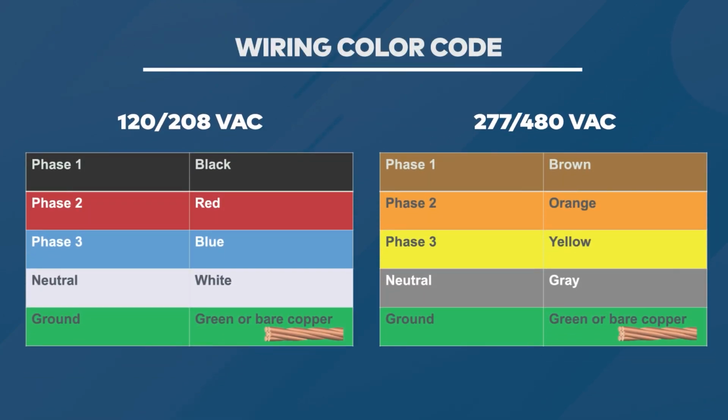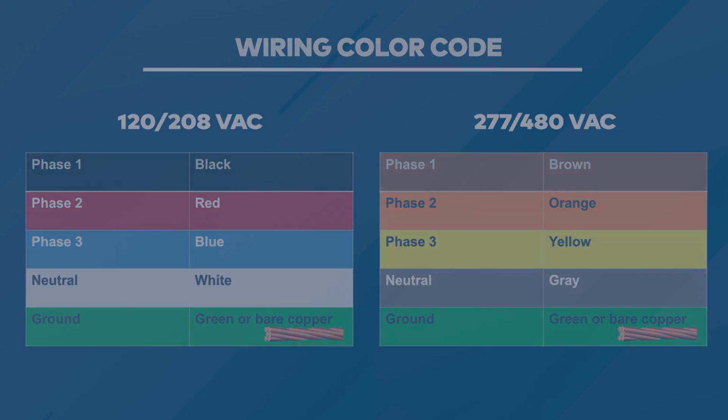Here is a quick reference for the wire colors specified by the electrical code to be used on each wire used in an electrical system. This specification must be followed so that electricians may safely work on and operate the electrical system, and very few substitutions are permitted. In a single-phase system, just the black, white, and green wires are used. In a single split-phase system, the red wire is added. Depending on the application, the ground wire is permitted as bare copper, without an insulator.